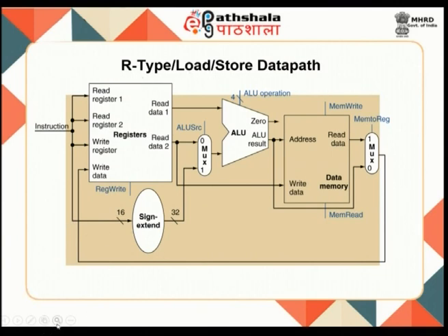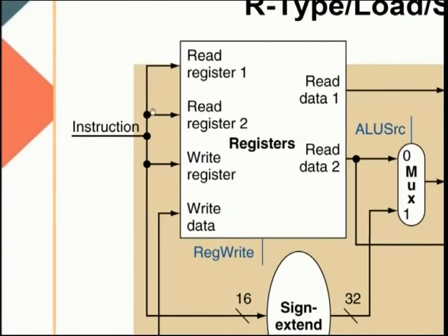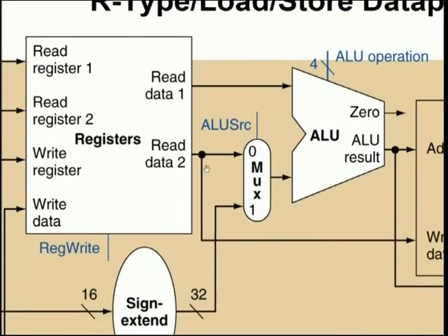So, as I indicated earlier, you have the instruction coming here, the instruction gets decoded, and based on the instruction getting decoded, that will go to the control unit, which will generate the various control signals. Meanwhile, because it performs a fixed length encoding, you read this register specifier, you read the second register specifier, you read the register into which you have to write the final result, and then you have your ALU operation here.